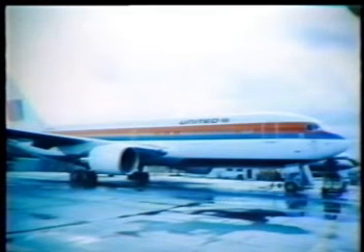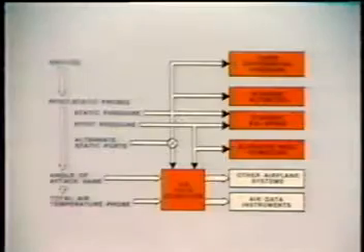These drains are concentrated in 3 areas of the airplane: on both sides of the forward equipment center, on both sides of the main equipment center on the support columns of the electronic racks, and in the aft cargo compartment. Pressure lines connect the probes and ports to several pressure-sensitive devices inside the plane. These devices are cabin differential pressure, standby altimeter, standby airspeed, elevator feel computer, and the air data computers.